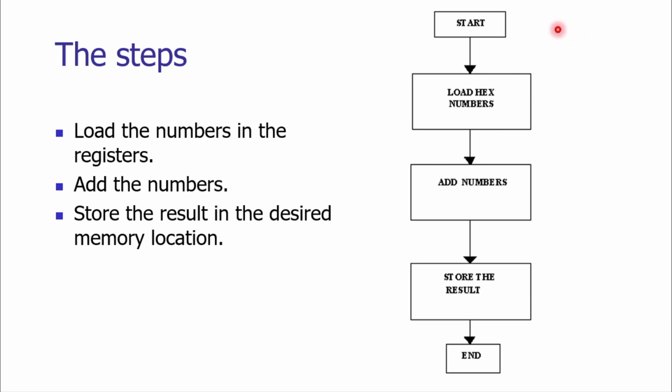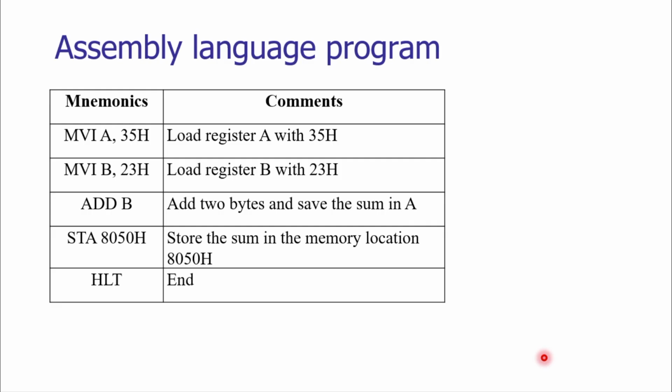For that purpose, we can develop a simple flowchart: start, loading of hex numbers, then addition and storage of the result. After that, the program will end. The corresponding assembly language program for this operation can be seen on your screen. These are the mnemonics. Mnemonics, as we have seen, are special words of the 8085 which designate specific operations.